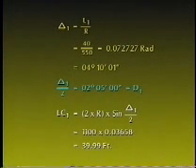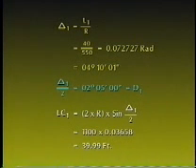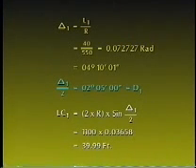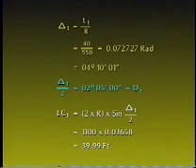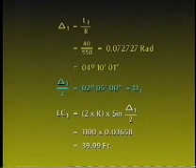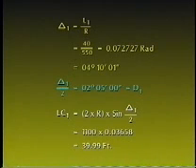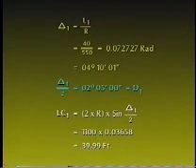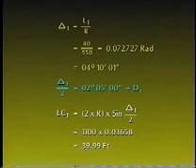Three calculations are shown on this sketch: determination of delta sub 1, determination of half delta and or deflection sub 1 for the same arc sub 1, and determination of the chord sub 1 for the same arc sub 1. L sub 1's central angle, or delta, is determined by dividing L sub 1, 40 feet, by the radius, 550 feet, which equals 0.072727 radians, or 4 degrees, 10 minutes, and 1 second.